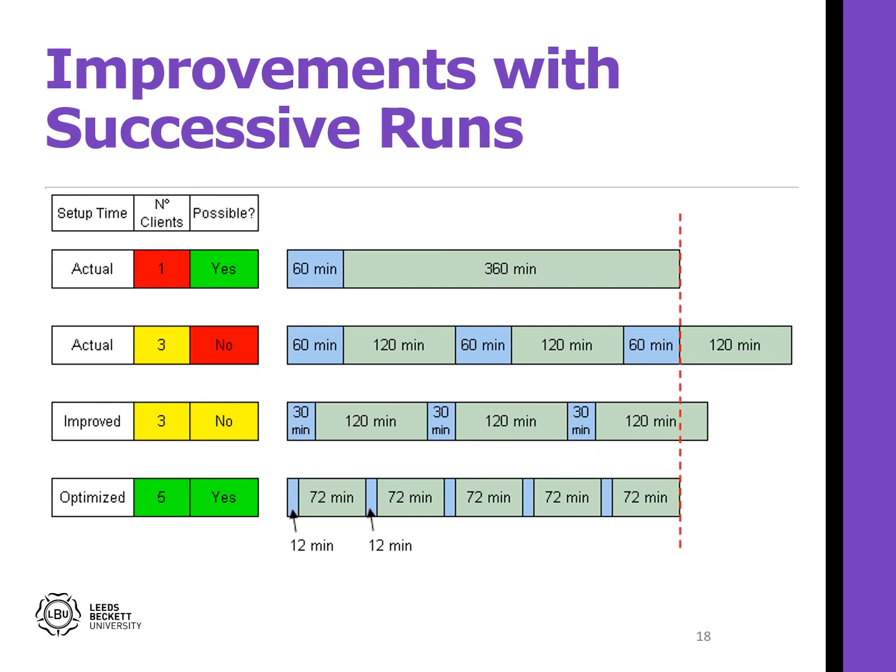So say the first one is red, blue, green, yellow. If you're waiting for a yellow one of these products, you could be waiting for days with the current situation of a 60-minute changeover. Like I say, you'd run for 360 minutes just to pay off the 60-minute setup time. A lot of companies spend a lot of time reducing the time to make the product, and not enough time thinking about the changeovers as well.